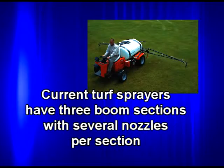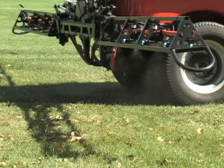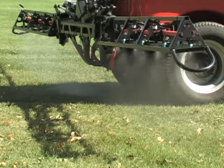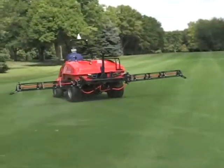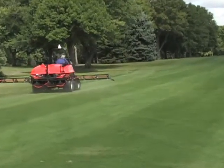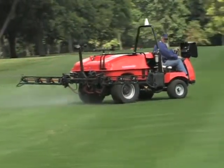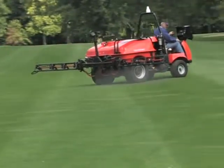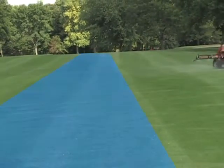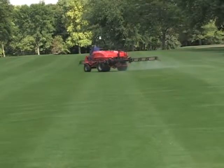Individual nozzle overlap control. Current turf sprayers have 3 boom sections with several nozzles per section. Sharpshooter with Invisio Pro and Switch Pro provide 10 sections, allowing the possibility of individual nozzle control. With this technology, individual nozzles will now automatically and instantly shut off as the boom passes over areas that have already been applied. It automatically and instantaneously turns the individual nozzles back on when it encounters unapplied areas. Finish passes or skips can be sprayed with only the individual nozzles required for complete coverage.